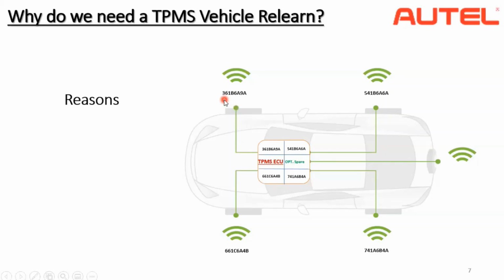And this particular tire pressure monitoring system sensor, which is on the front right, has the same code, the same ID, stored in the ECU for that particular location. And it's the same case with the sensors at all 5 locations.